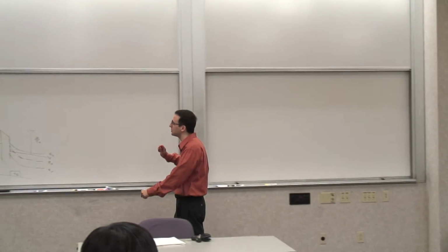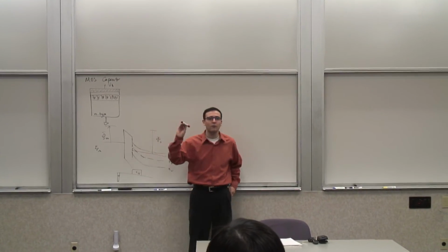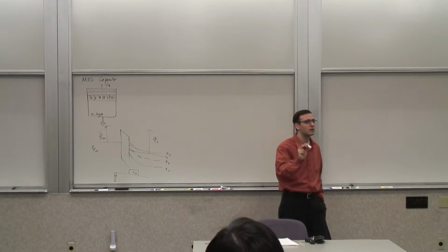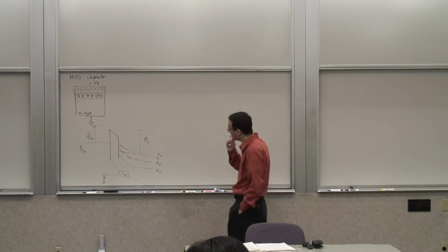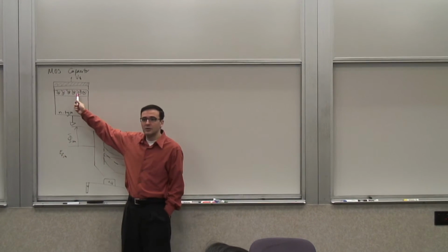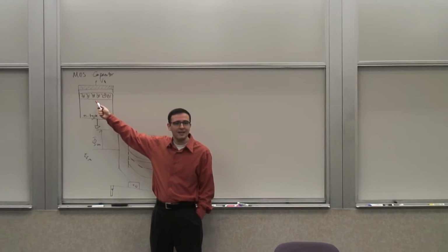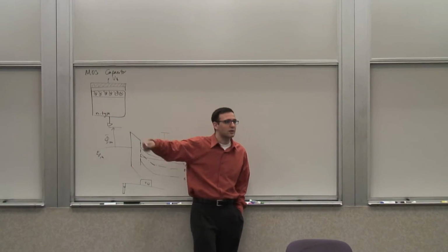Or, in electrical terms, if you have current flow, you can have constant DC current flow. You're not in thermal equilibrium, but you could be in steady state. So you have to make a very clear distinction. And Fermi energy, this Fermi distribution, is only for thermal equilibrium. So you have to realize that. So that's important. And that's why we saw different behavior when we hit this thing with different kinds of frequencies or different kinds of waveforms.